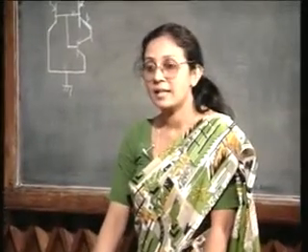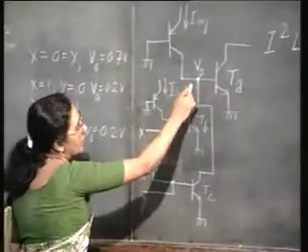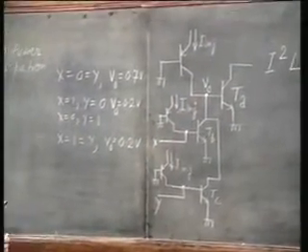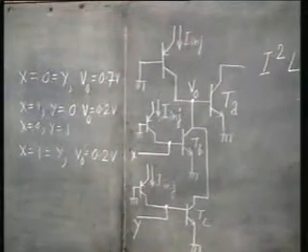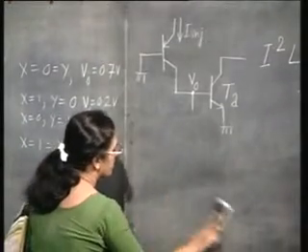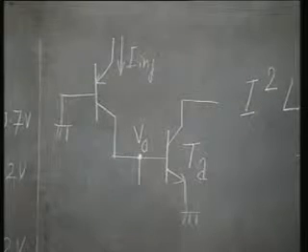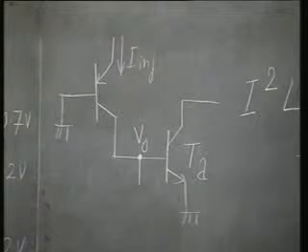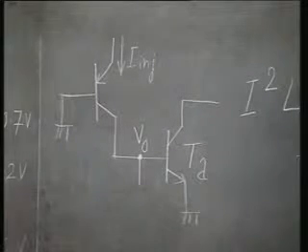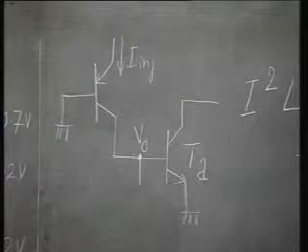And there is another advantage which will be evident to you if you just concentrate on one building block. Let me rub off all the other extraneous matter and just concentrate on this one building block. This building block is replicated any number of times in the I square L. What do you see? I have a PNP transistor and an NPN transistor.